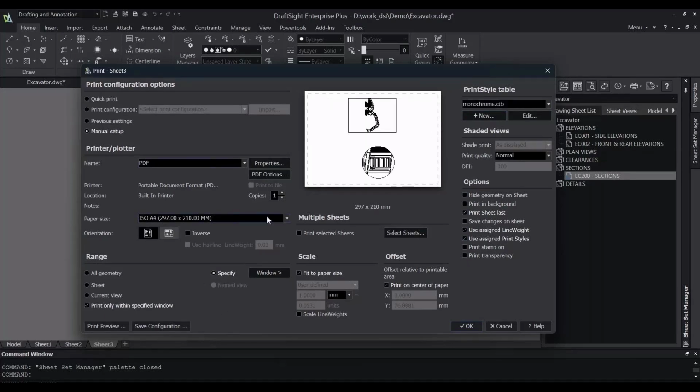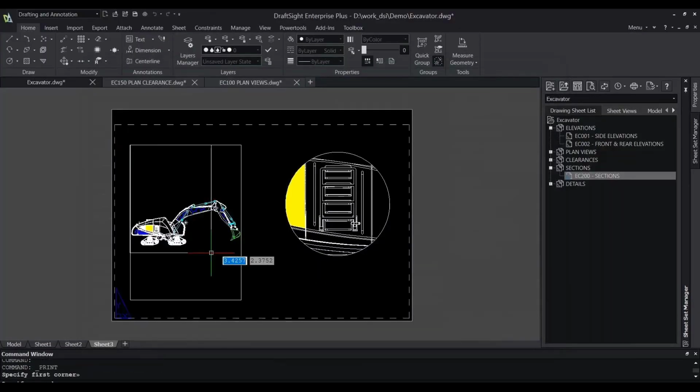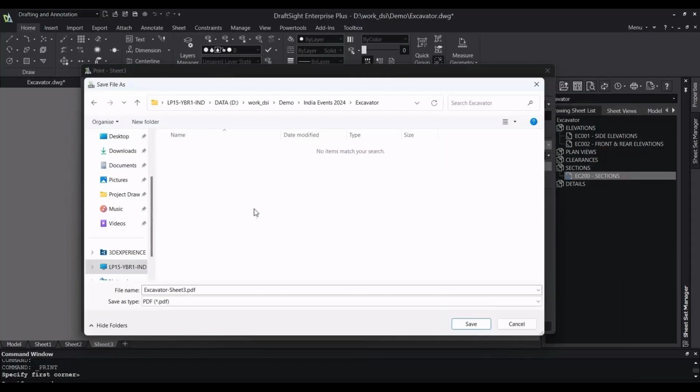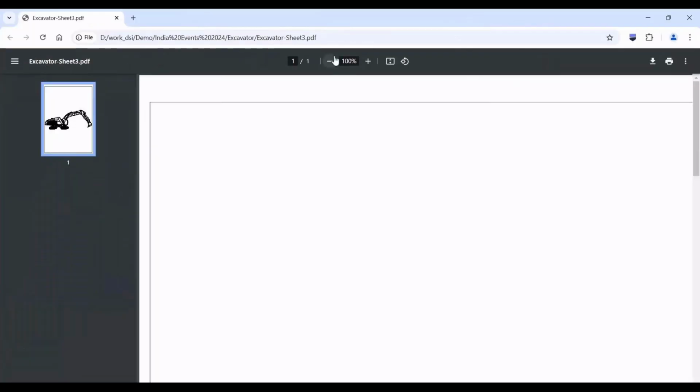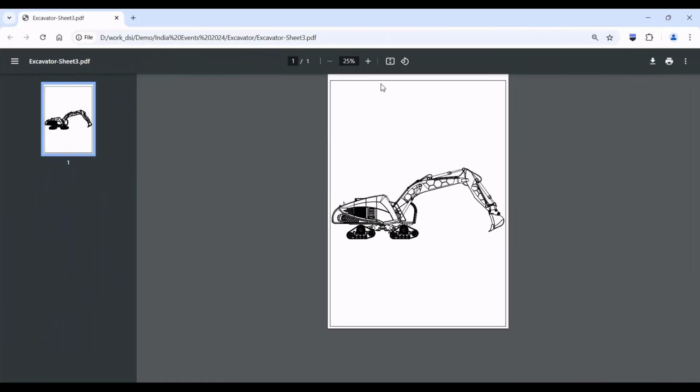And then different kinds of sizing or shaping of your PDFs can be done. And this tool, wherein I can select which area I want to print, is extensively used. So you all must be knowing about it. Once this is done, I can save the print configuration, and a PDF is also saved over here. If you see, a PDF has been saved from my drawing.